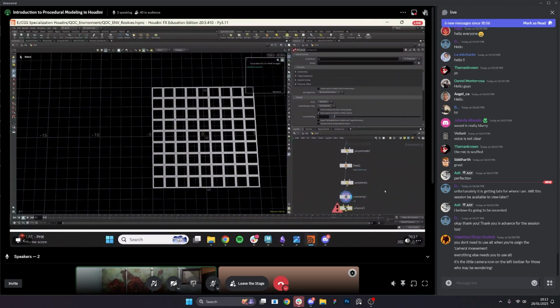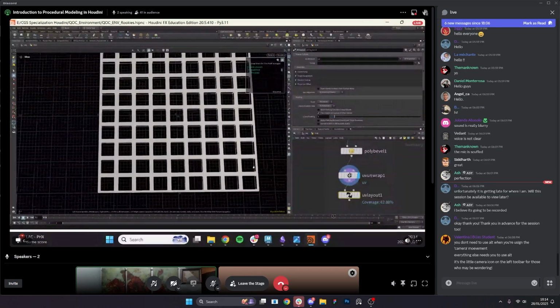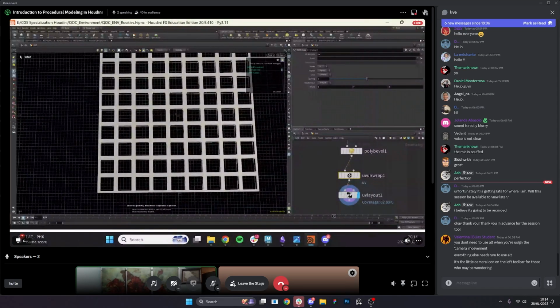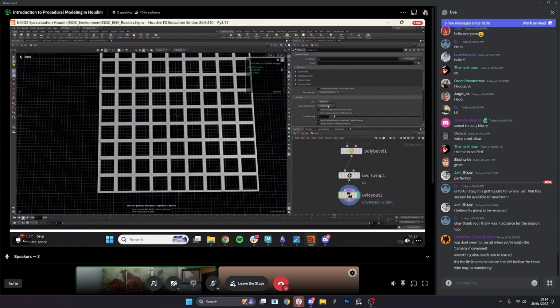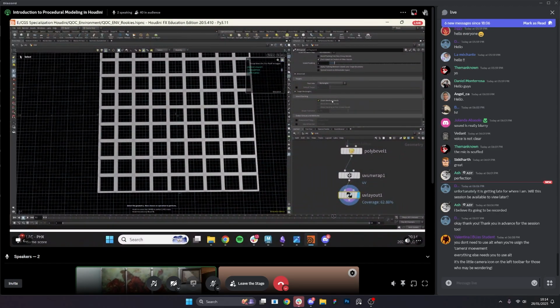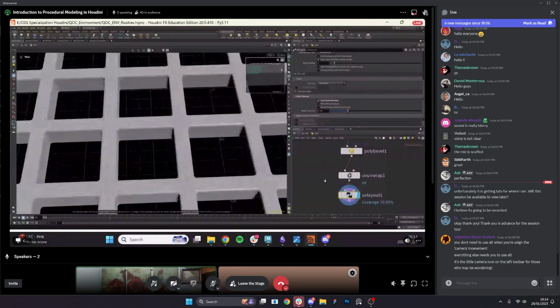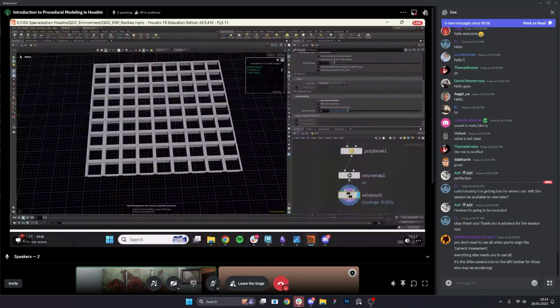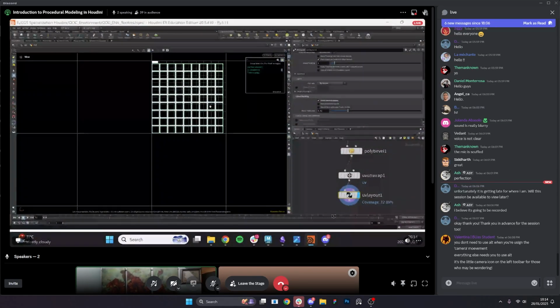I don't know how many of you have done grid type of objects, but if you've ever tried to do UVs in Maya with an object that has this many edges to cut, it's a tedious process to say the least. So we've got a UV layout. I'm leaving these at default, by the way, the UV unwrap. The UV layout, I'm going to change to stack identical islands so that it doesn't give me these faces all as separate pieces. Well, it'll all be basically stacked on top of each other. So we go and we've got our UV viewport.